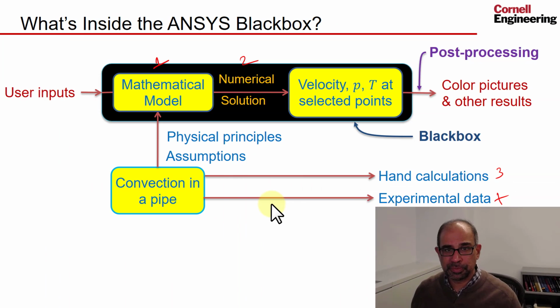We have seen that the mathematical model is a complicated boundary value problem, much more complicated than what you would get in conduction. Let's think about how the ANSYS Fluent Solver will solve it for us using the finite volume method. So in the process, I'm going to give you a whirlwind tour of the finite volume method, focusing on the big ideas and particularly the errors introduced and how we can minimize those errors.